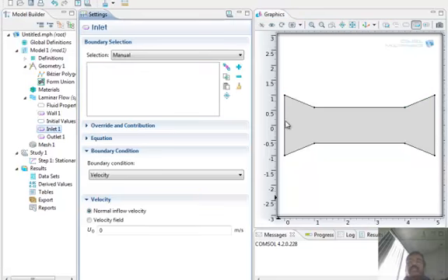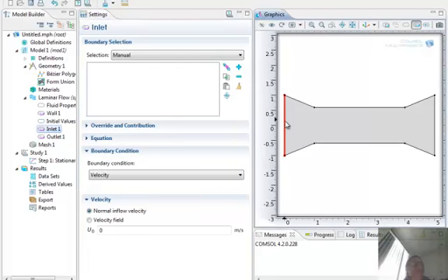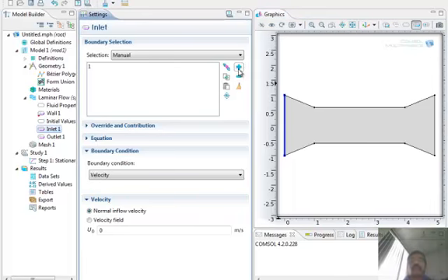So I can just go there and click on this boundary. It highlights that with red, and you can assign it any property. So I'm going to call that my inlet. So I have assigned it to the inlet, so I add that one. So that line segment 1 is now an inlet boundary. Okay, then you have to say, what is the velocity? I can go in there, that is the inlet velocity. I can put a value of 1. That is 1 meter per second. Okay.